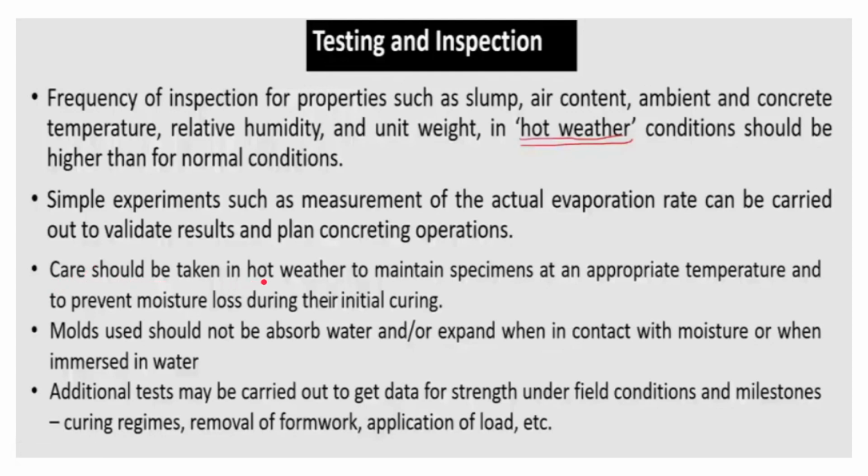Care should be taken in hot weather to maintain specimens at an appropriate temperature and to prevent moisture loss during their initial curing. These are some fundamental things we have to keep in mind. Molds used should not absorb water or expand when in contact with moisture or when immersed in water. So molds should also be tested, so that they don't absorb water or expand.